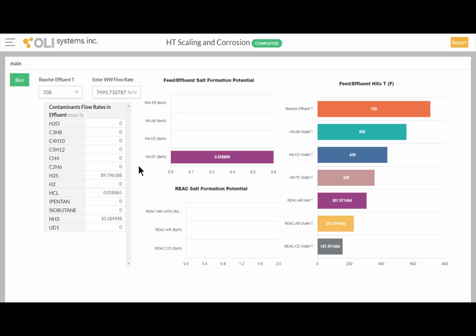Now, this kind of question in a refinery, and this is a diesel hydrotreater, maybe I should have said that earlier, is asked constantly from the process team to the reliability team, where they're constantly asking, can I lower my wash water flow rate? Now you can create a tool and give it to operations, so the operations can answer that question themselves and really accelerate the time it takes to make these decisions, especially in areas where water is scarce or it's a commodity, right?